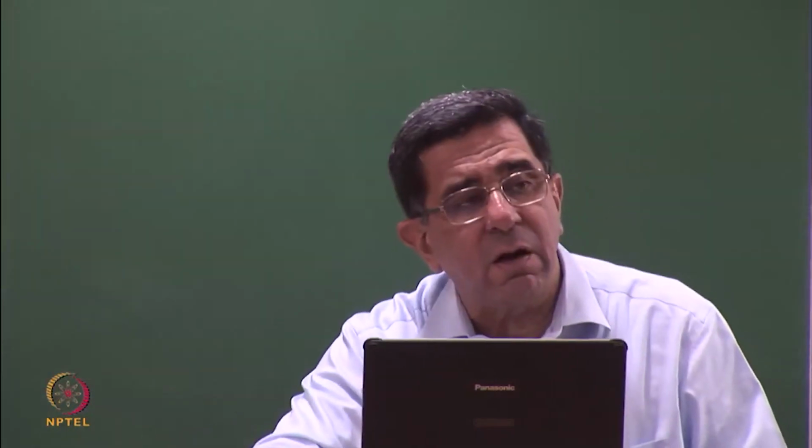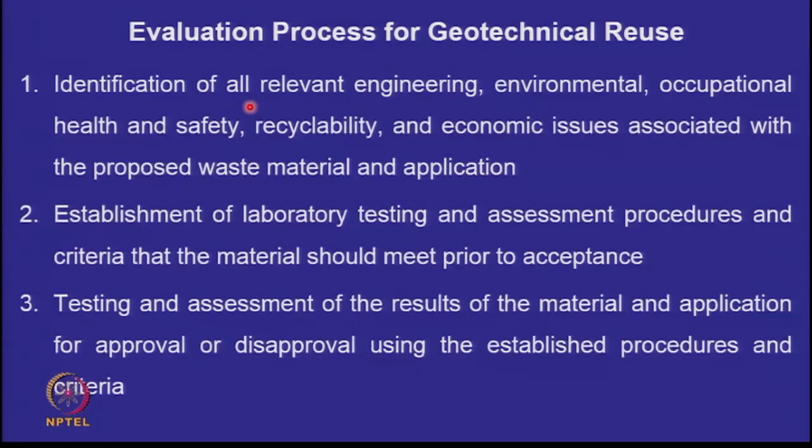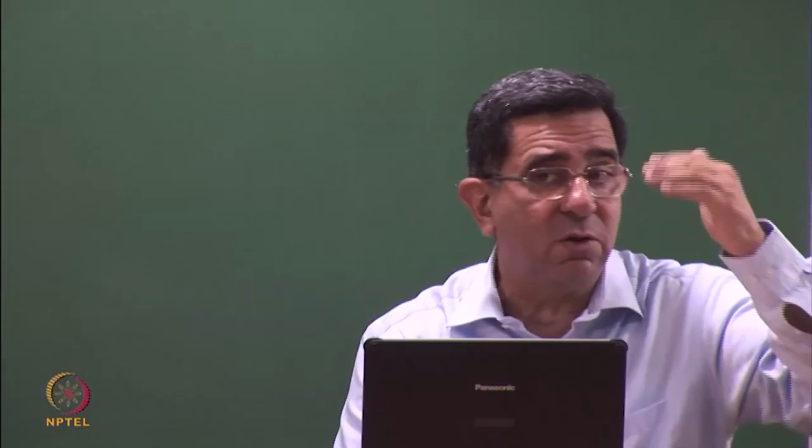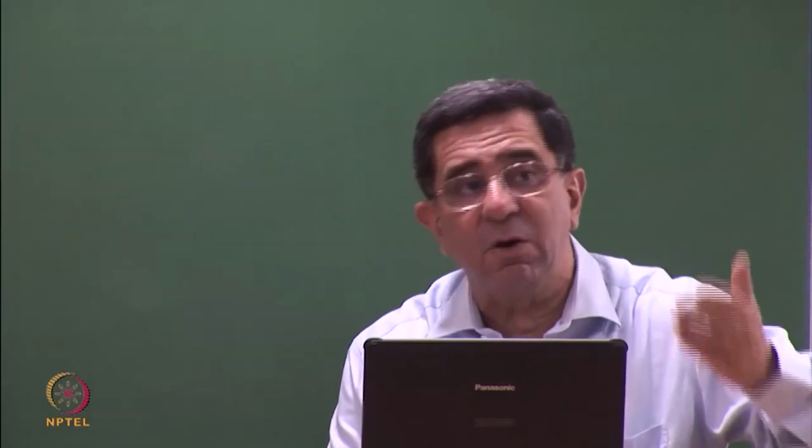But for wastes, at every location, all engineering, environmental, occupational health and safety, recyclability and economical issues are to be understood. You have to have very rigorous laboratory testing and assessment procedures for all the points that I gave you in the beginning, and you have to be able to have a criteria for approval or disapproval using the procedures. And if you are going to do the TCLP test, you know all the values beyond which you can't use it and below which you can use it.